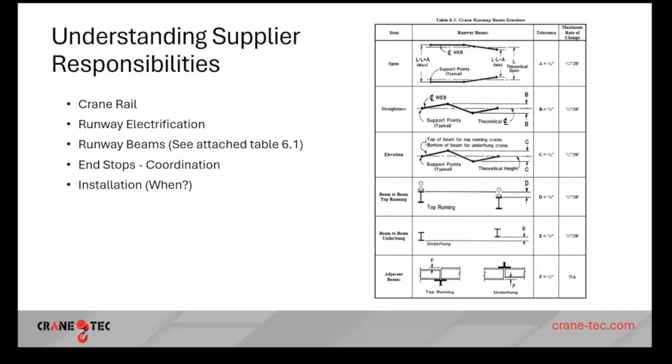Yeah, so it's a real world project, and for the sake of the agreement we usually have in the MBCA, I don't want to name manufacturers or anything like that, but we have a building that's roughly 80 feet tall that has 2 separate cranes that are long span over 100 feet. So we get 3/8 tolerance on those according to the charts. And the plumb tolerance for the exterior columns is about 1 3/4 inch, 1 13/16, something like that.